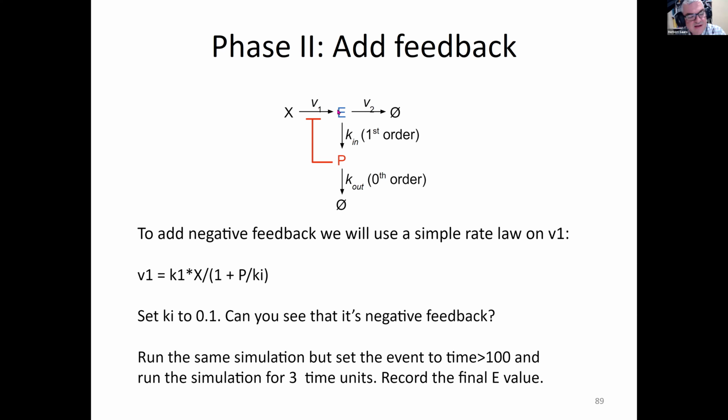Whereas if E is slightly off, P will integrate that difference, right? And originally you saw that P was a straight line. It's a straight line because it's integrating a constant level of E. Remember, an integral of a constant is a straight line, okay? So it's actually an integration. And that's why this works, okay?